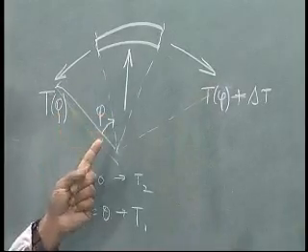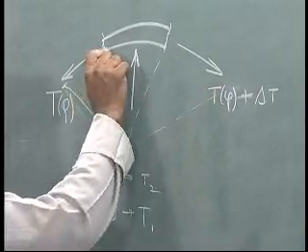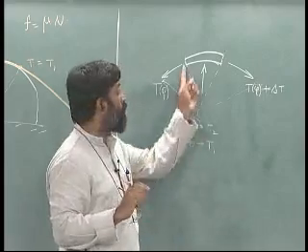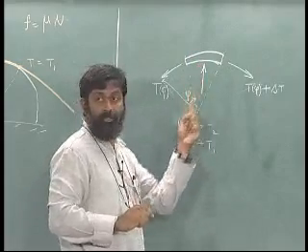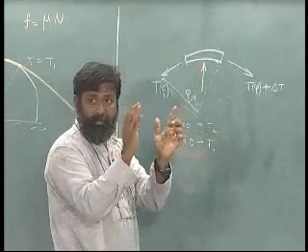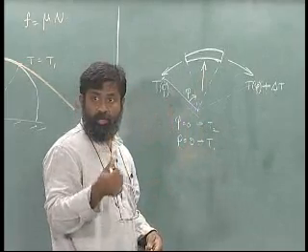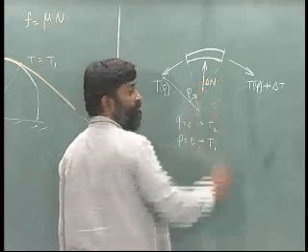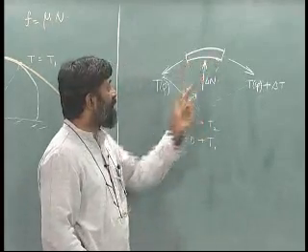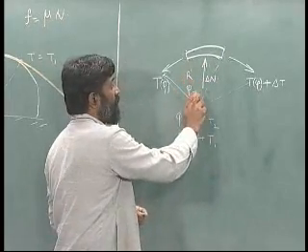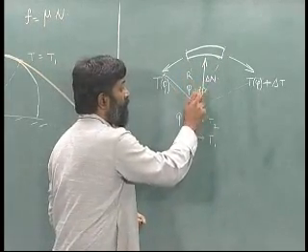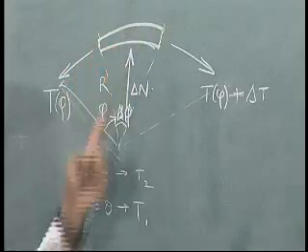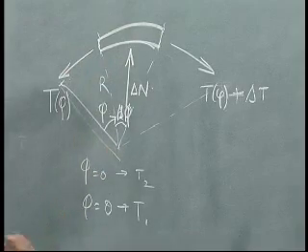Alright. The normal reaction is nothing but the pressure that is provided by the surface onto this belt, the resultant of which is shown over here. If the size becomes smaller and smaller, the normal reaction is also smaller and smaller. So, let me call this delta N, okay, and this depends on r times delta phi, which is the angle that this subtends over this particular point, alright.